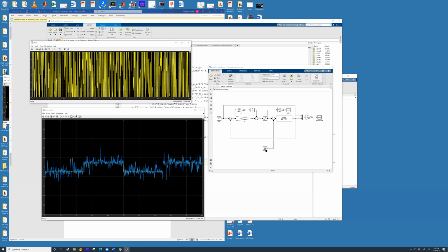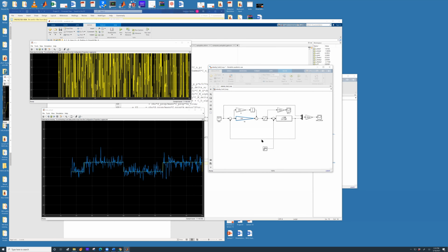So the way this is implemented, and this is a little bit interesting, in the first iteration, you don't have noise. At this summing junction, this disturbance gets added. It passes to the transfer function, and now the disturbance is fed back along with the feedback, and now you have this Kp. So let's see what happens if I increase the value of Kp. See if it is able to reject the disturbance.